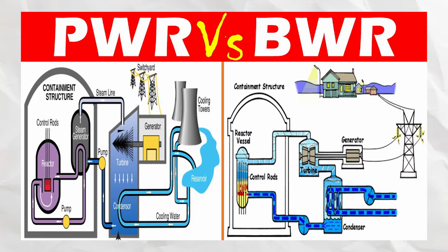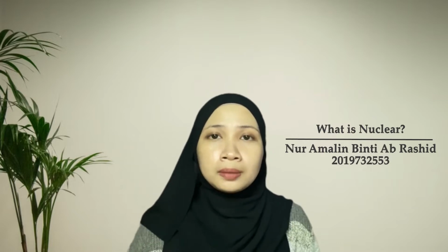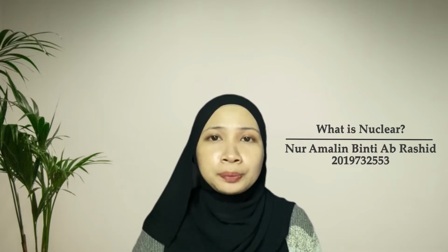A light water reactor is a power reactor that is cooled, and also moderated, using ordinary water to keep the system cool. There are two major types of light water reactor: the boiling water reactor, known as BWR, and the pressurized water reactor, known as PWR. The difference between BWR and PWR is the boiling method for steam. PWRs constitute the large majority of the world's nuclear power plants.